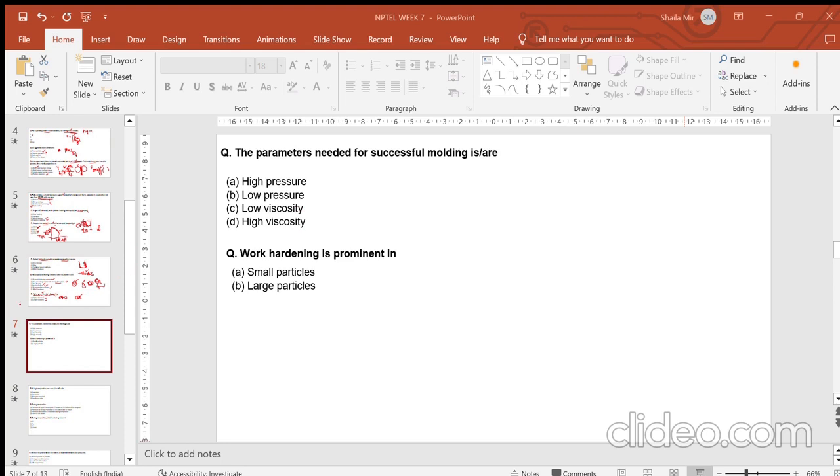So this is another point, and also the efficiencies of these mills is very less. They are not very efficient because obviously if you are taking, for example, 1 gram of your feed, you have to take 10 grams of your balls. So you are basically using the energy for rolling or milling 11 grams, but out of those 11 grams only 1 gram of the material is actually being milled.